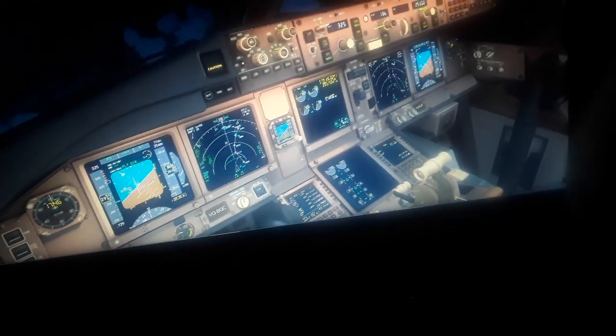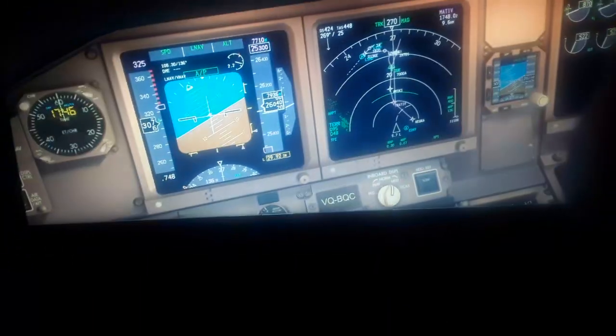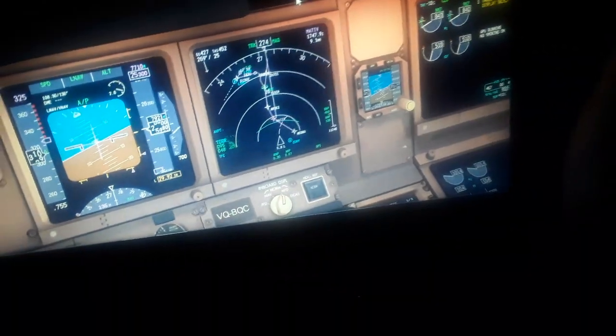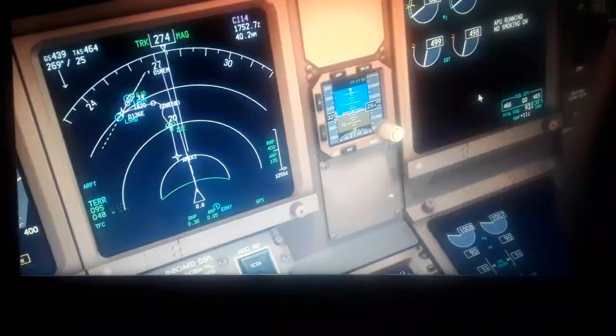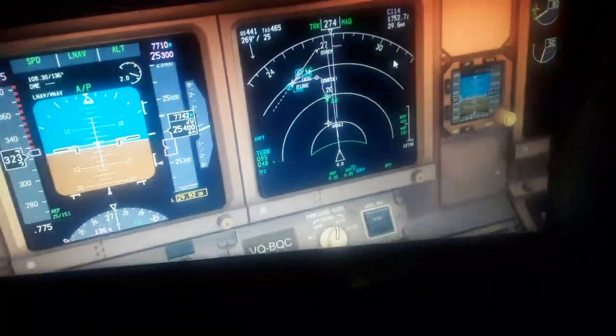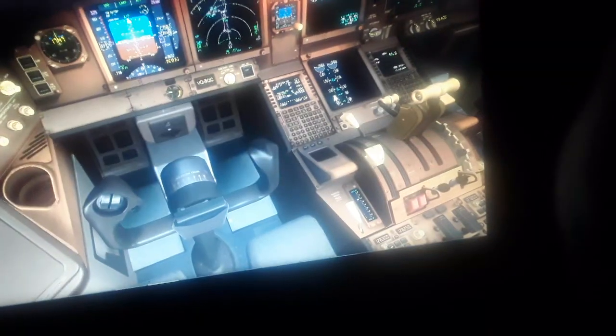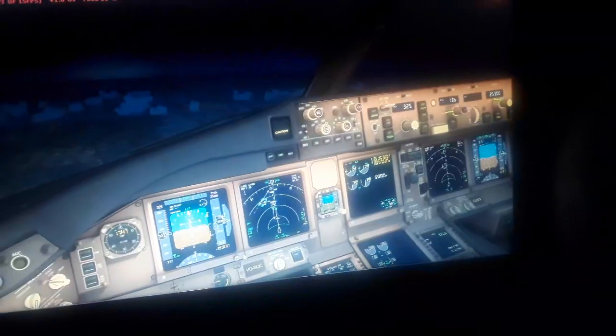So we have 8 minutes left for this flight. Perhaps we can connect the autopilot as per display and set the altitude now. Also the approach reference, we'll select the last waypoint here. And also the approach airspeed. Like this. So we're gonna level off and we're gonna have to start descent in a couple of minutes.